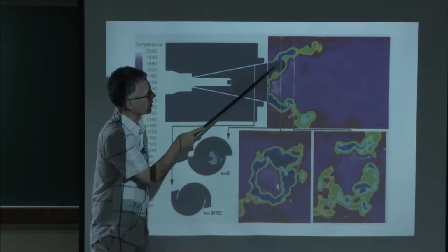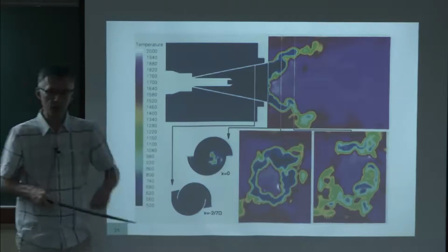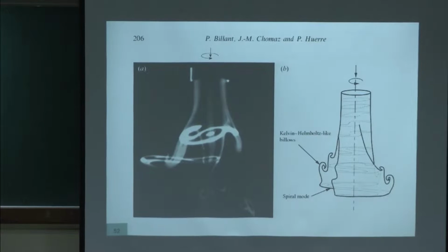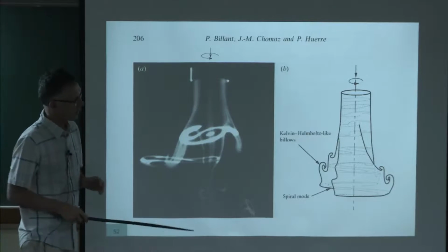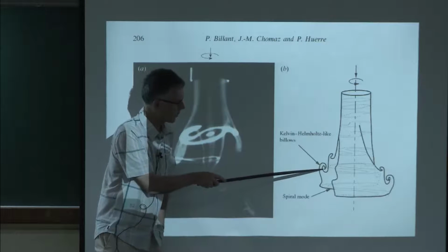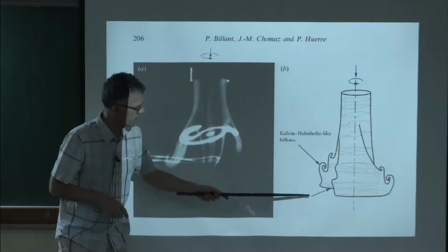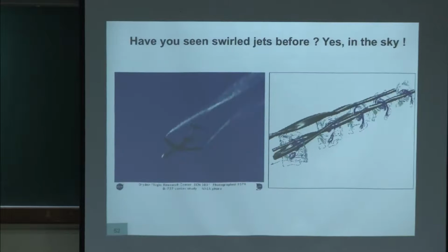You see, after a few centimeters, everything's burned almost. So that's really useful to have a compact flame. So that's good. The problem is that swirl is a very unstable fluid mechanism. It exhibits all kinds of problems. Not only the fact that here you have a shear layer, so you create vortices, but also the fact that globally swirl can exhibit what we call spiral modes, and those things are a problem.